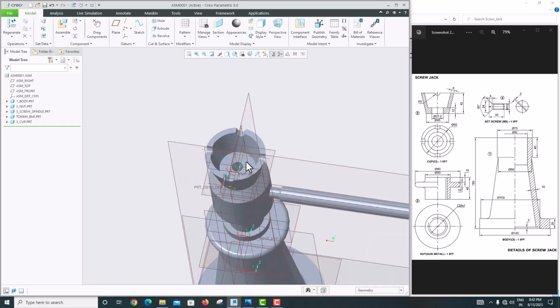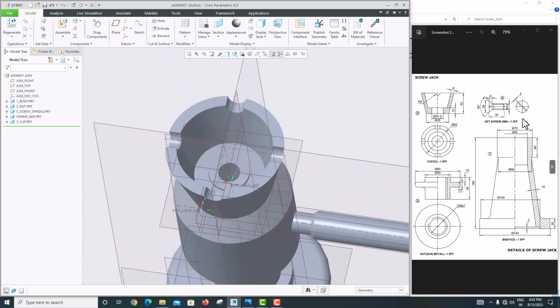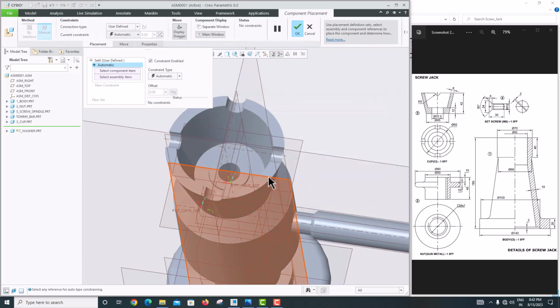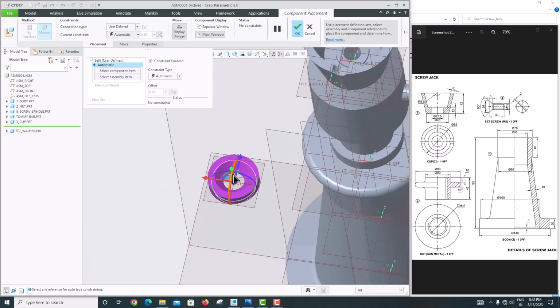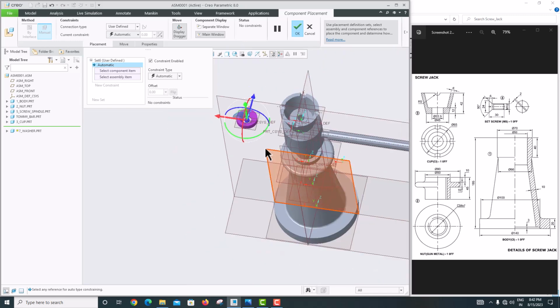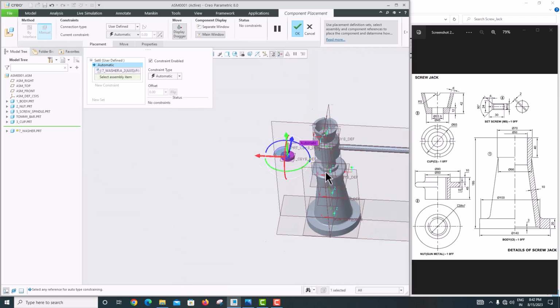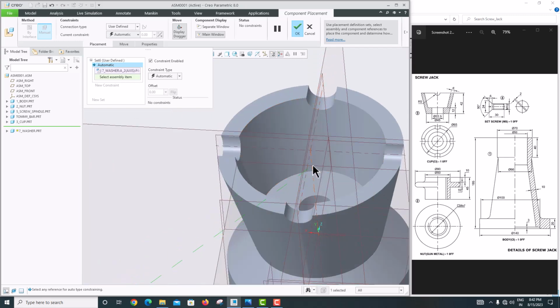Finally we just want to keep these two, the screw and the washer. First take the washer and put it here. Go to assembly, washer, the washer has come. There is an axis for the washer, and there is an axis for this cup also. Make that coincident.